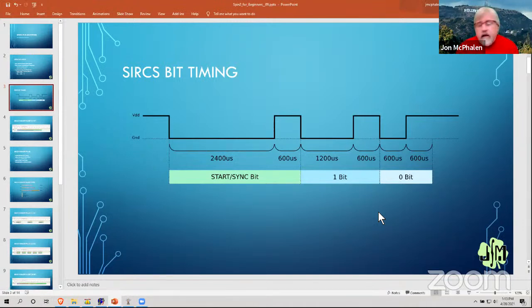you can do, and I've got a project that does that, the baud rate is roughly between 500 and 800 baud, depending on the combination of bits, because you'll see that a 1-bit in total is 1800 microseconds, where a 0-bit is 1200 microseconds in total duration. So you don't have a fixed timing; even if you have 8 bits in a byte, the timing of a byte can vary depending on the configuration of ones and zeros that make up that byte.